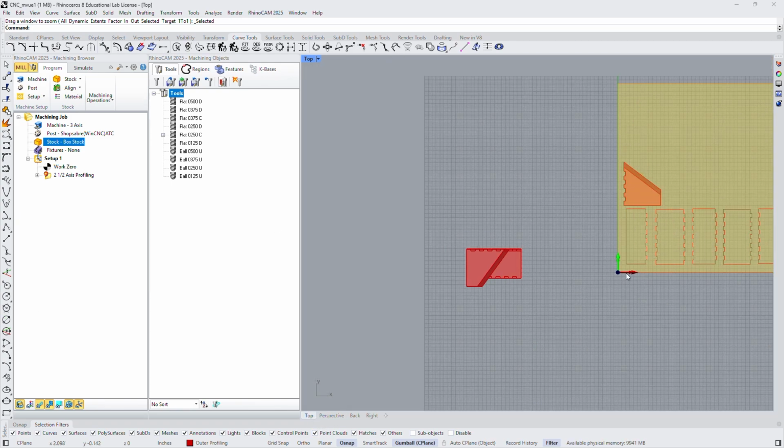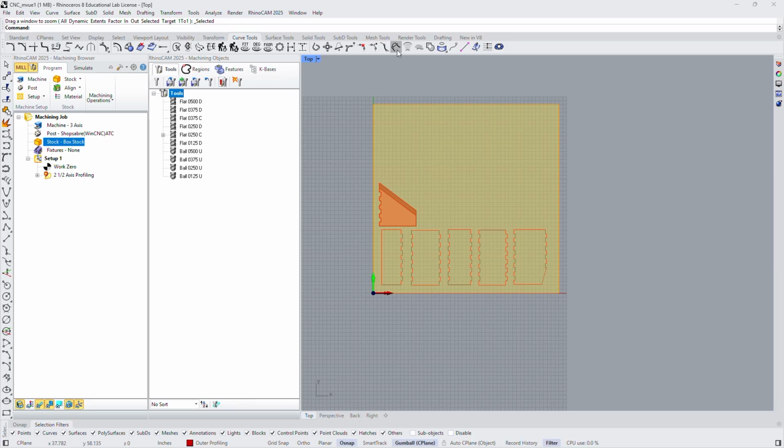For the purpose of making a representation at the end of the process for our staff to have a visual aid along with the packet they get, I'm going to draw a new rectangle too. So I'm going to rectangle, first corner is 0, and then 48, 48, just so we have some concrete geometry there. And then I'm going to drop some dimensions on there as well. So 48 and 48. Ta-da. Okay, so we have our setup here.